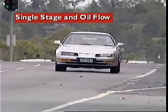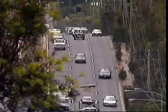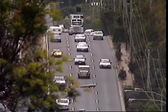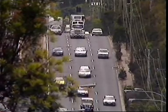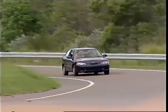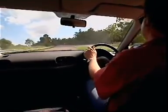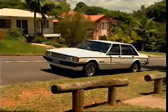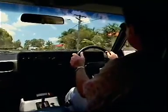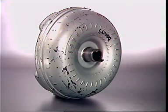The purpose of a light vehicle transmission is to transmit engine torque to the driving wheels. It also has to provide for this torque to be increased or decreased to suit differing road and operating conditions. In a manual transmission, this is done by the driver manually selecting gear ratios to suit. In an automatic transmission, it is done by both the transmission control system automatically selecting the gearing according to load and speed, and by the torque converter.